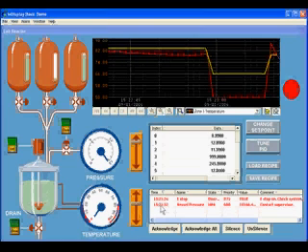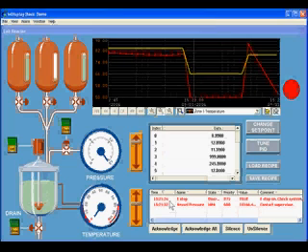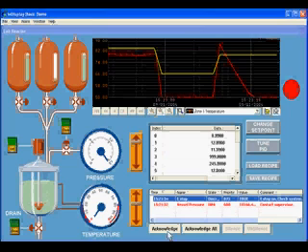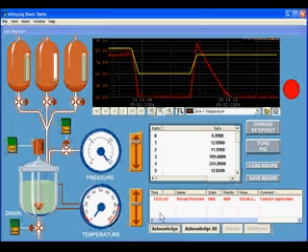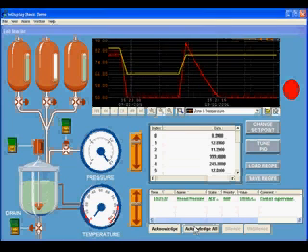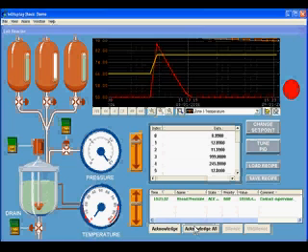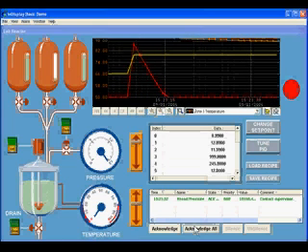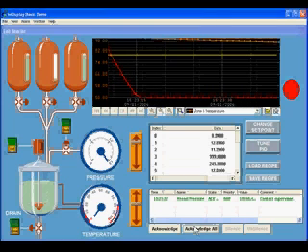We can change our set point by changing the position of the slider. Another feature is alarming. Here is a detailed alarm screen where we can acknowledge or silence alarms. To acknowledge an alarm, just click on it and choose the Acknowledge button. To acknowledge all the alarms on a screen, choose Acknowledge All. You can also create historical alarm logs. Other alarming features include sending values to other tags on alarm or acknowledgement, persistence, alarm priorities, alarm notification pop-up windows, file or printer logging, and sound triggering.